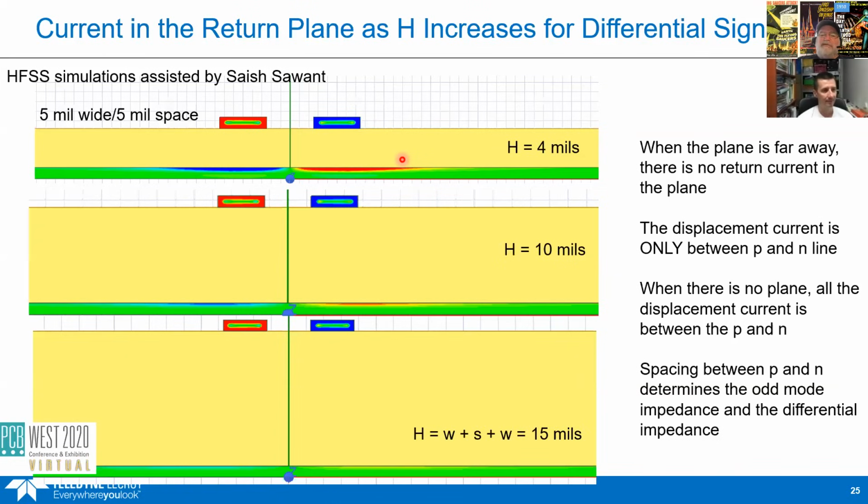And we set up this problem as a really, really simple problem just to help us build that engineering intuition about how the currents flow. So here's the first case: a typical board, well, we're only looking at 2 layers, the signal line and the return, with typical thickness and line widths for a 4 or 6 layer board, tightly spaced, so it's tightly coupled. And look, where are the return currents?